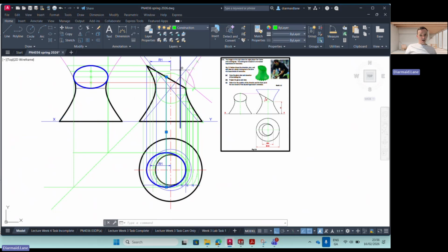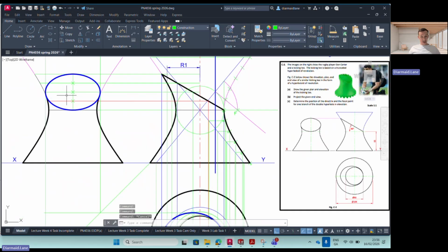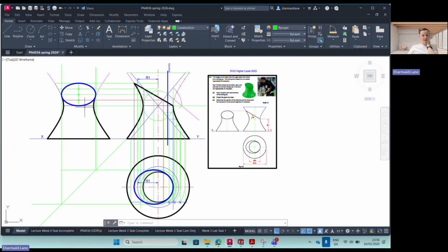And obviously it's going to be across on that central line just there. So that'll give you your 4 points of your ellipse. If you can do that, it's manual drafting. You're going to have to maybe use a template or whatever. Using AutoCAD is pretty straightforward. You just have an axis, and then another top or bottom of this axis here. So that is that.